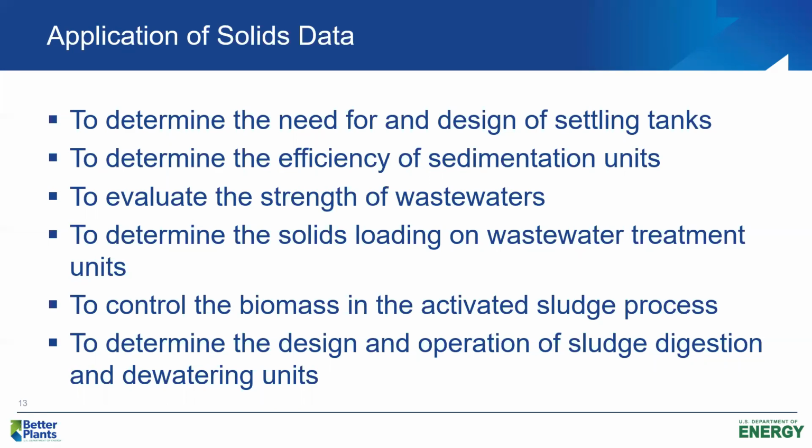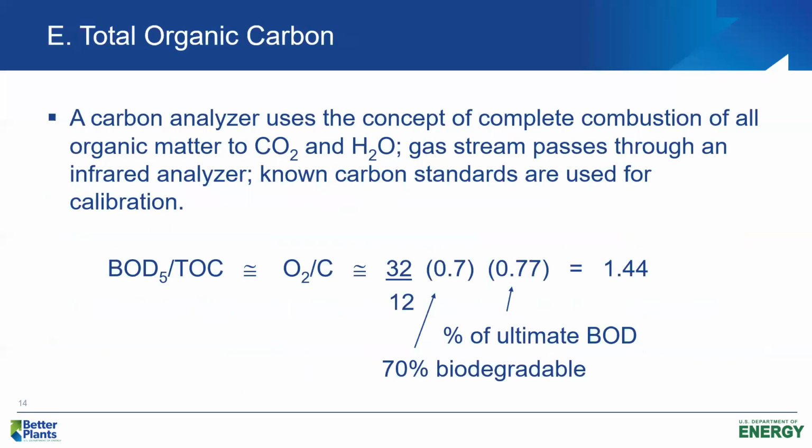Helps us calculate the age of our biomass, and that is extremely important in controlling the process, determining the age of the bacteria, and getting the process to operate in a way that will give us our best effluent quality and achieve other operating goals that we'll get into later. Solids data, we use that to design sludge digestion processes and also dewatering units.